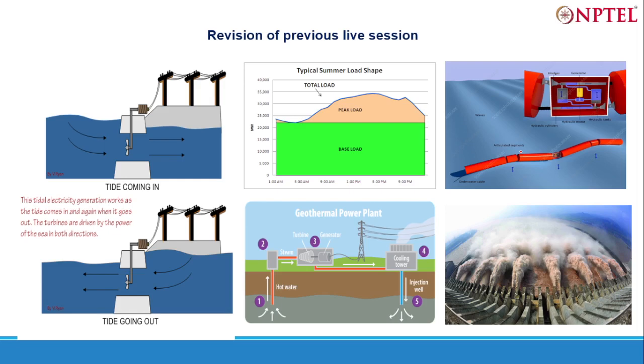In that, what happens is we take the hot water and convert it to steam. Because it is taken as hot water, we just need to supply bare minimum energy to convert it to steam. And you know what happens to steam? We pass it through the turbine. It rotates the blade in the turbine. That blade is placed on a shaft, that shaft is coupled to a generator, and it produces electricity.